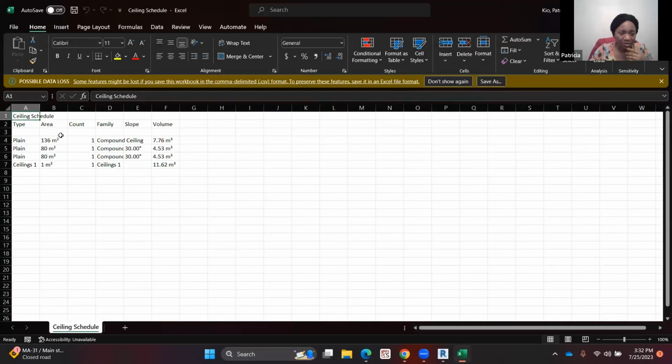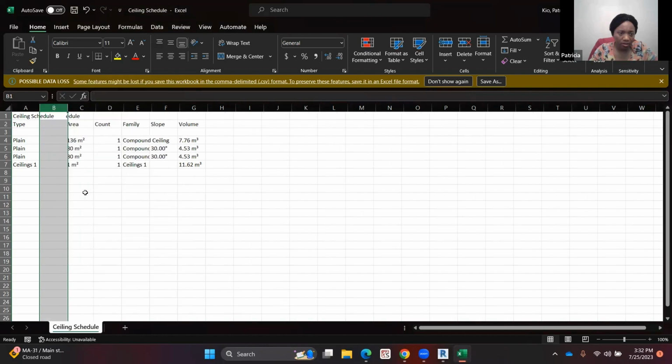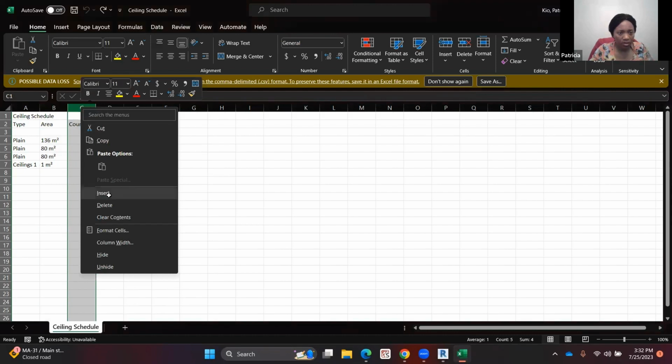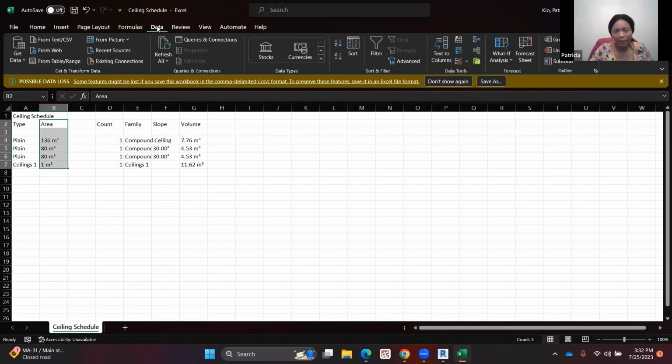You see that you have an Excel sheet with your quantities. So you want to work with this further now. What we need to do, we first create another column here. Control Z. And I'll click here to create another column here. And then if I select this box here and say data, and then we do our text to columns, where is that text to columns here?